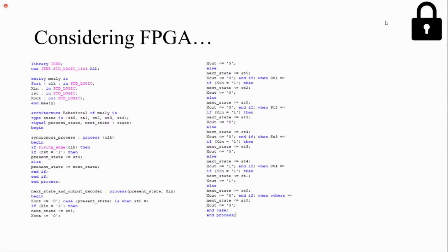So here's my code when I just tried to do this to see what it would be like. I basically just followed my original state diagram to do this. So I still have 5 different states, and I map through each one, either if the x in is 1 or if it's 0, so it can either go 2 different ways, 1 or 0. And then in 2 cases, the x out is high, which is when the 4th matching bit is detected on my sequence detector. So when either 1110 or 1101 is detected.